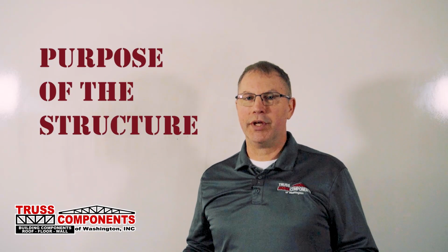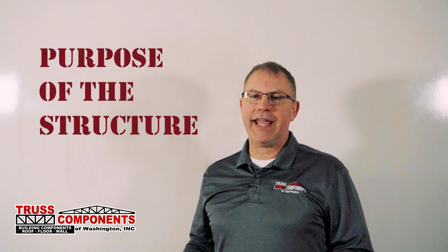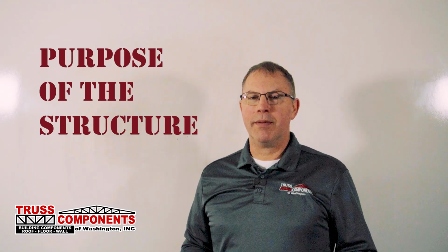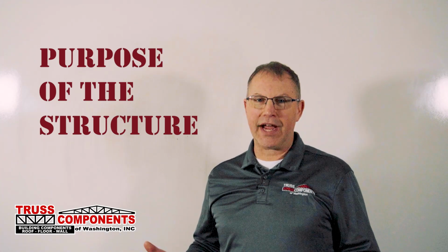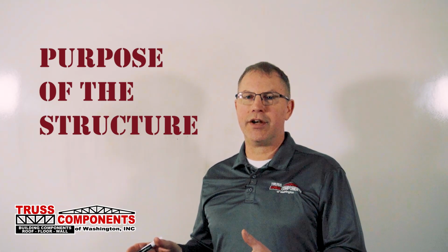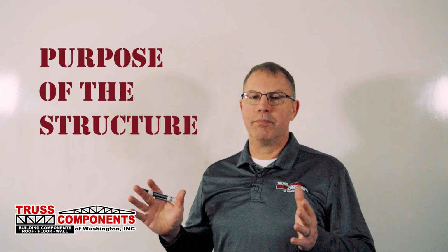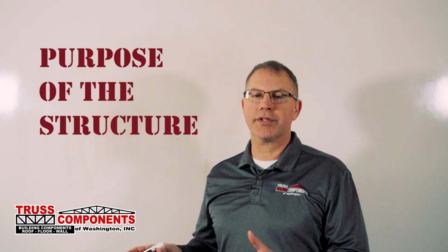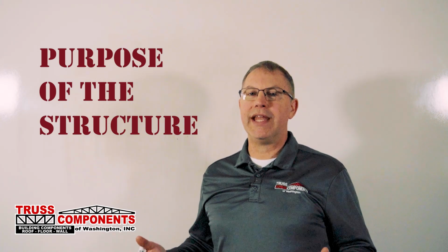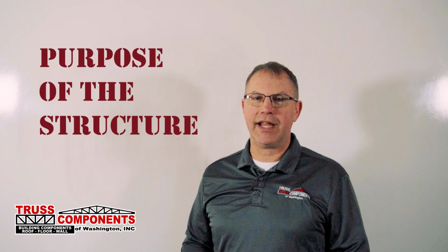Lastly, number 8, we need to know what is the building going to be used for. Different types of buildings get different design considerations based on what we call an importance factor. So a fire station is going to be built to a higher standard than a backyard shed or a pole structure that will be housing animals. And so we need to know what is the purpose of the building, and that way we can design it to meet the specific codes that it is going to be subject to.